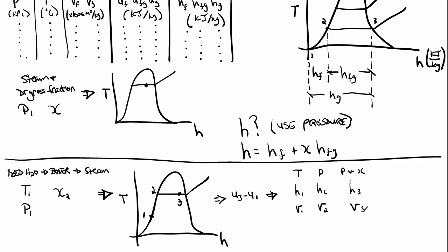But remember this: you can find internal energy 2 with the pressure, find internal energy 3, but you cannot find it for U1. Doesn't work. It's because of these other variables: enthalpy, pressure doesn't affect temperature, okay? Not in the case of a fluid. Specific volume, essentially fluids are incompressible.